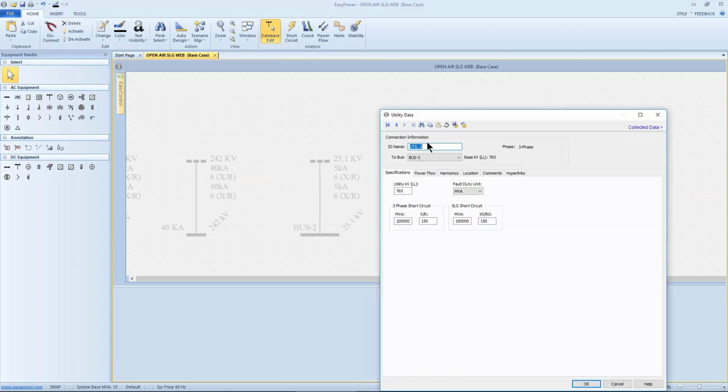Let's go ahead and relabel it, retitle it, and then set my, let's go ahead and pick out 50,000 amps as my upper limit on line to ground. So I'm going to leave 50K in here, 6, 50K, and stay with 6.